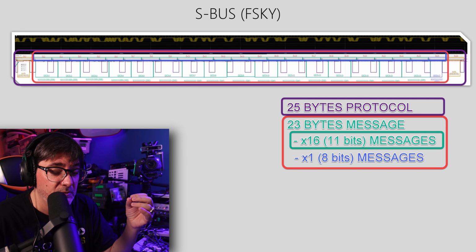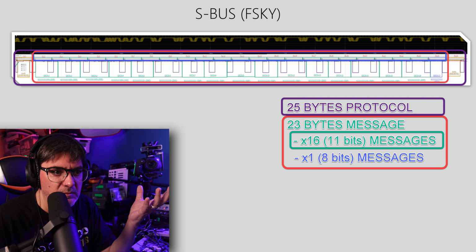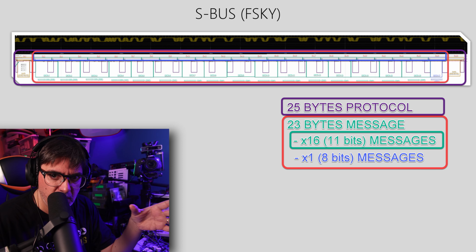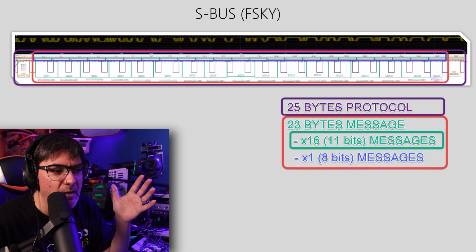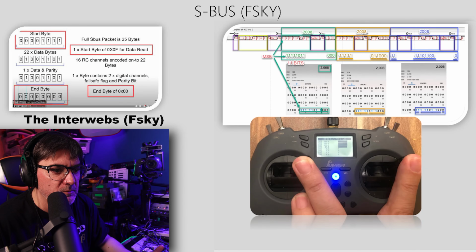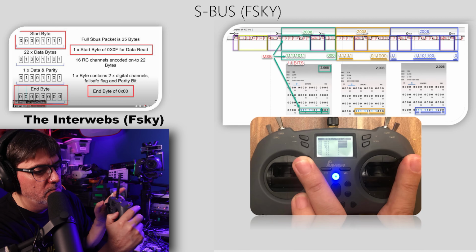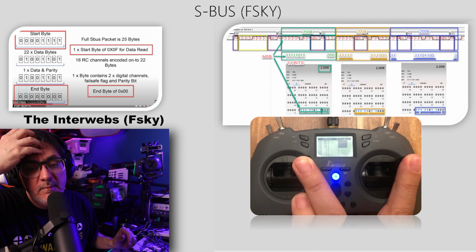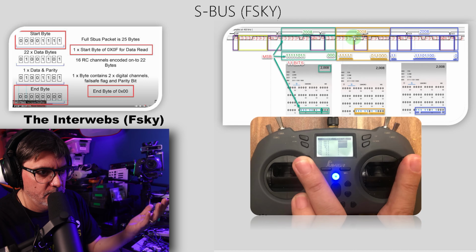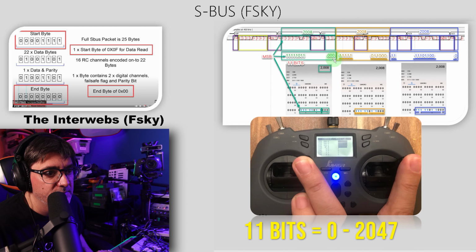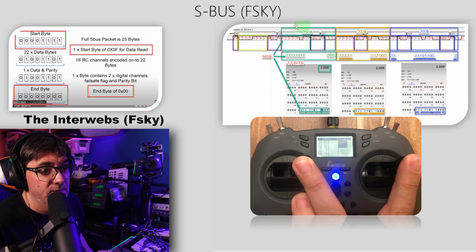So you understand that you're going to be able to read with the Arduino serial communication what's really going on, but you're not going to get the actual value that you need. So here's a good example. I'm sending all this information at maximum values, and even though it's a maximum value, it's not going to send me a full one. The maximum of each value is 2047. The maximum value that this controller is sending is 2008. So you can see how I'm grabbing the first 8 bits, and then I grab the last 3 bits from the next byte, and this is the information that I have.